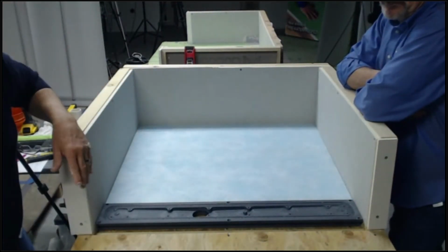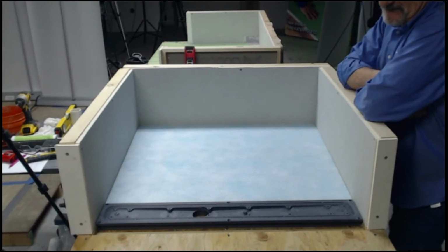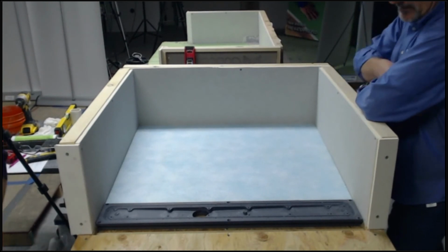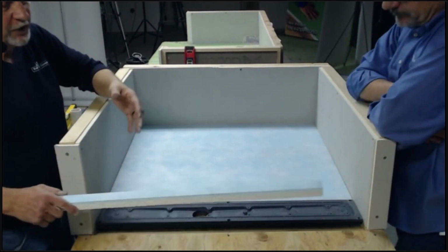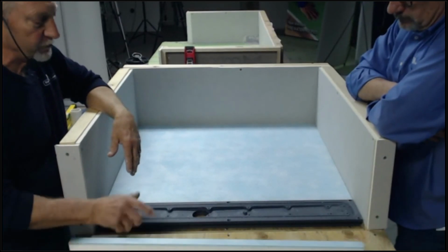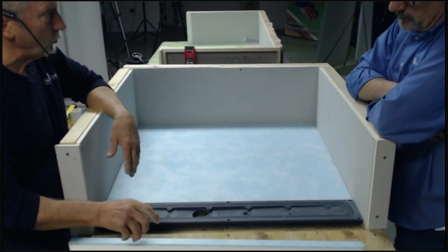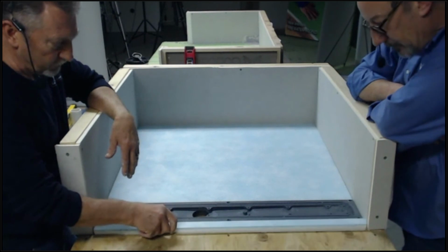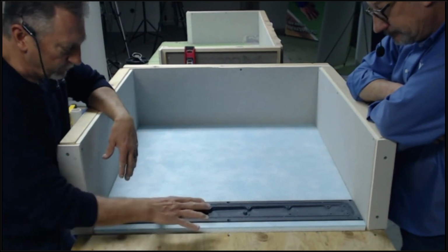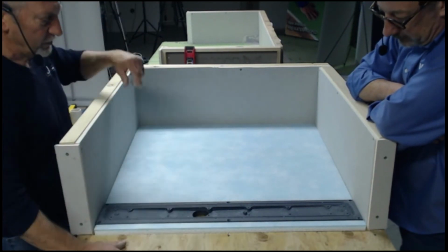And then now at the entrance of my shower, you see the gap right here. Yep. We have shims that come with this. So you'll just score and snap, cut the shim. They come 4.5 inches wide. Yep. I just cut a 1 inch shim and I stuck that right here. Modified, then set that in just like the multi-slope.